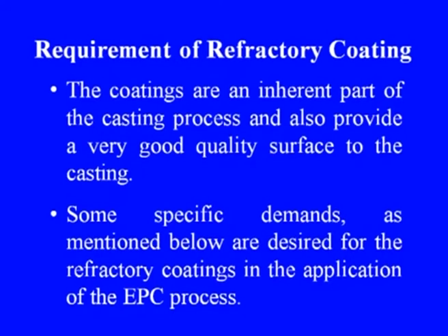Requirements of refractory coating. The coatings are an inherent part of the casting process and also provide a very good quality surface to the casting. Some specific demands as mentioned below are desired for the refractory coatings in the application of the EPC process. Highly permeable coating is preferred for rougher sand, while medium and low permeable coating is preferred for finer sand.